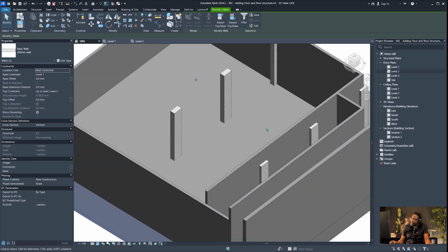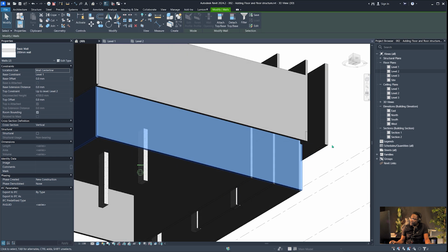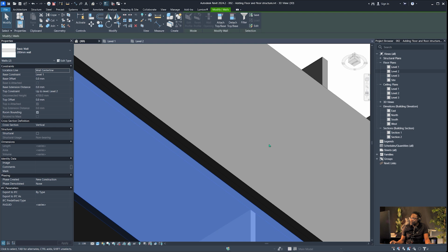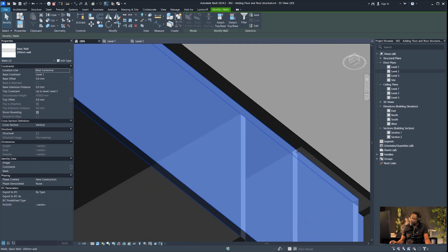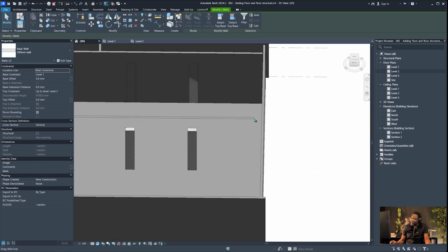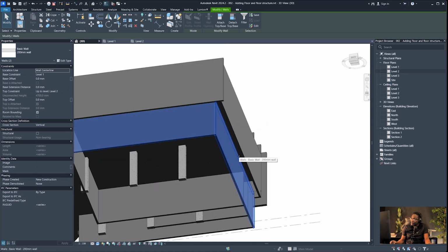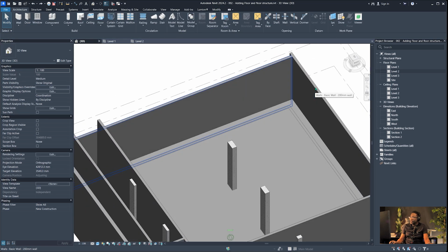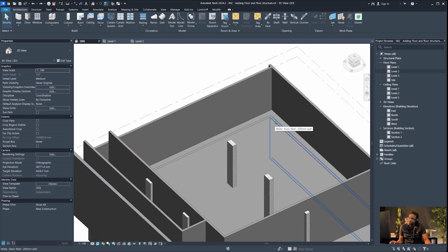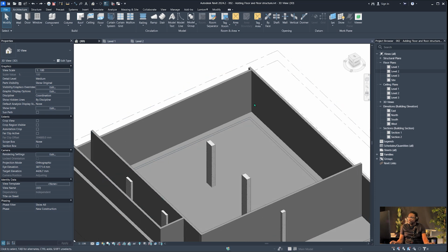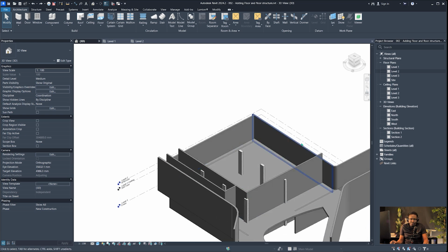But what I suggest is doing this later on, because what happened is that this model is not complete yet, and it is going to make certain decisions. So for example, notice that it adjusts this wall, and we may or may not want to have this wall on the height below the floor yet. So I'm going to undo that. We can always edit that when we are nearing completing the model, right? Otherwise you're going to find yourself going back and forward at this early stage. So that is how we get in the floor. Really simple.